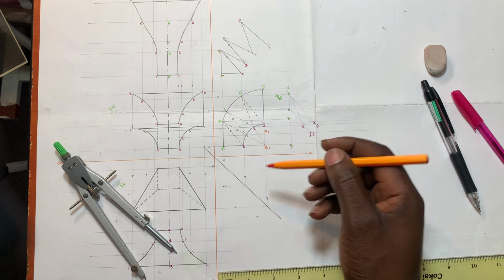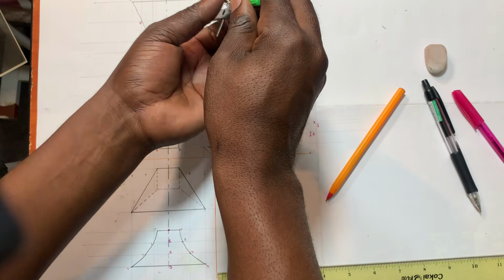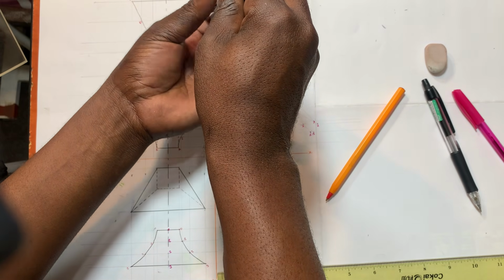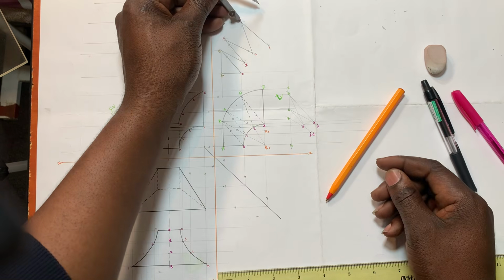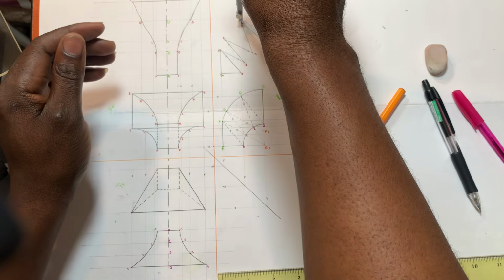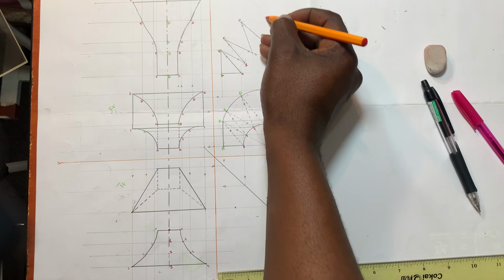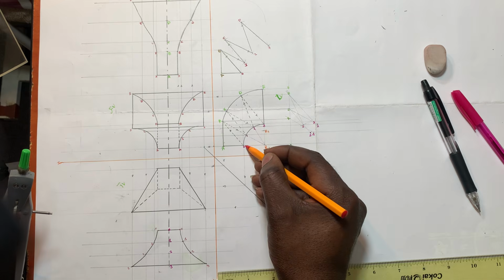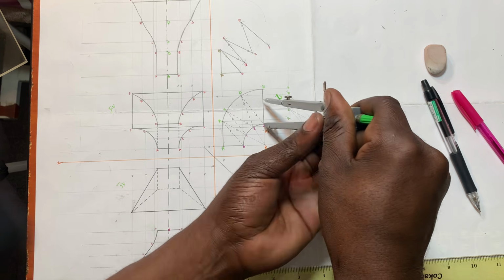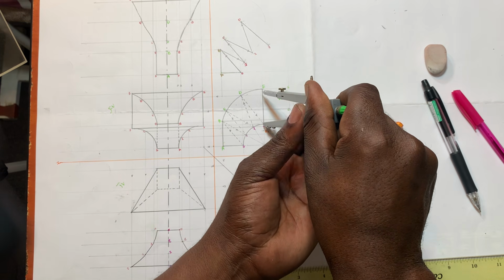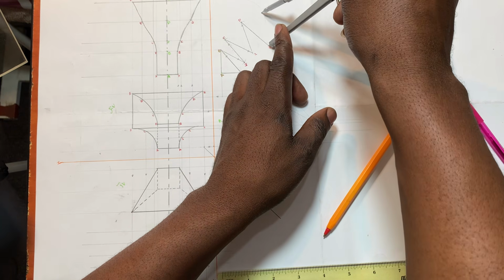So after that, come and place your drawing compass at D to E, which is your last point, which is that one. Now come and place it here at your development. Then you strike an arc, and this is A, B, C, D, E along this arc, which is 0, 1, 2, 3. So now I can simply place it at 3, further extend it to E, which is this one. So now come and place it here and bisect the arc.